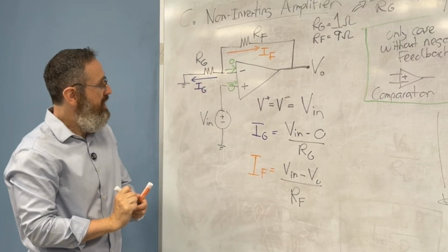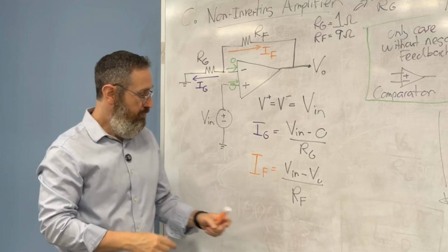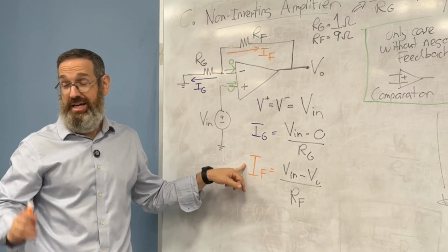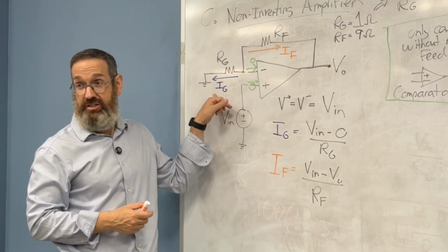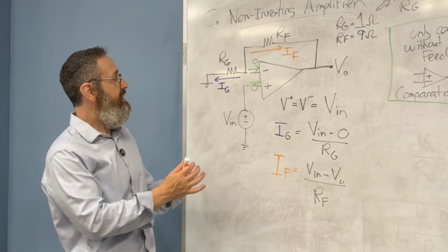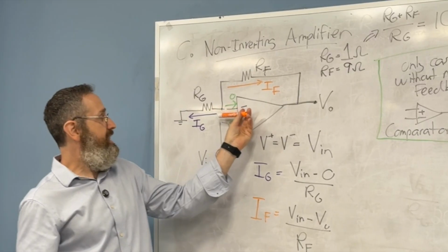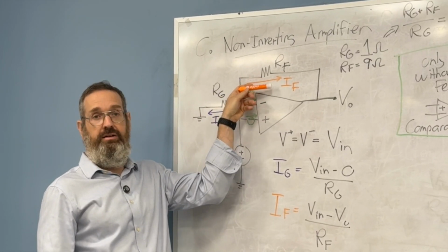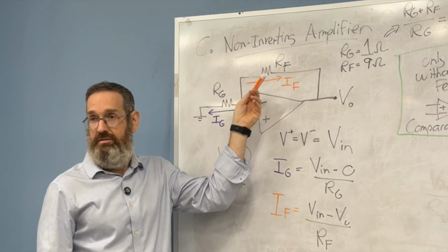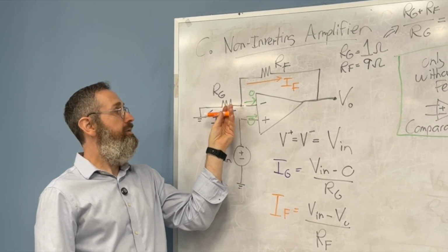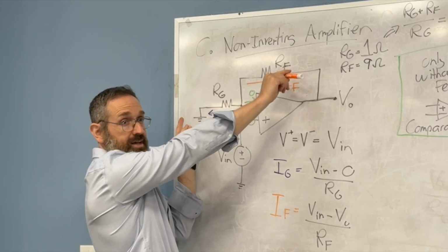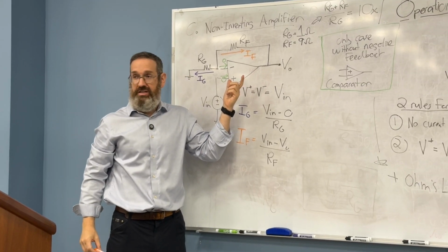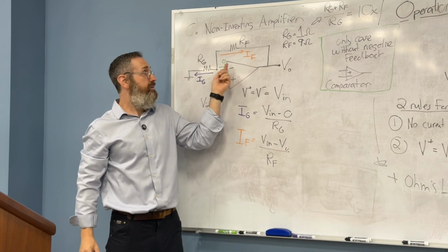Now, at this point, you might be tempted to say, well, I sub g is equal to I sub f. And this is why you're asking me about writing negative I sub g, because there's a little bit of a trick here. If this here is 10 microamps, this can't also be 10. This has to be negative 10, right? If this is 1 milliamp, this can't also be 1 milliamp. This has to be minus 1 milliamp, which you have sort of avoided in this course, up to now, talking about negative current. But here you see it has to be that way.